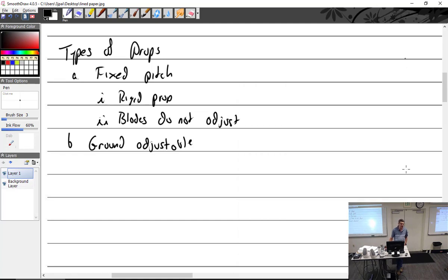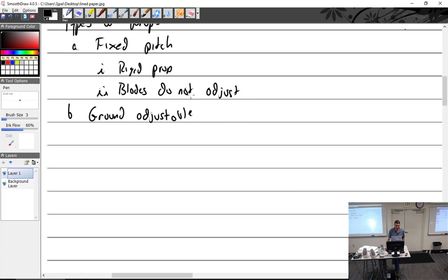And so what we're seeing is a resurgence of composite props, which is a fancy word if you cut them open, a wood prop with fiberglass on top of it. So composite props are making a huge comeback. MT propeller, big. Everybody's talking about MT props, and they're putting them on a lot of different things. Much lighter, kind of cool looking. So anyway, fixed pitch props getting hard to come by.